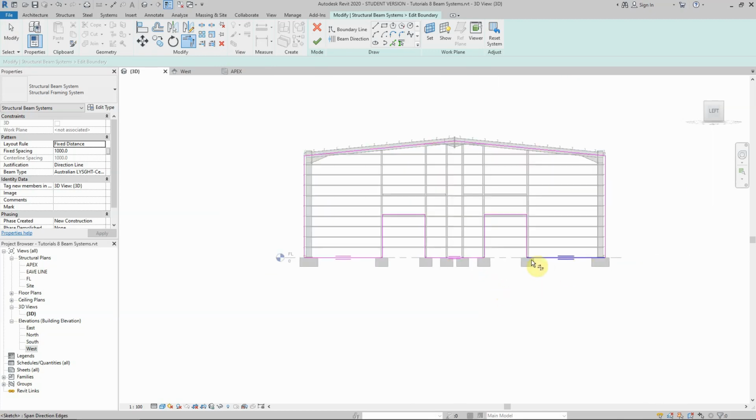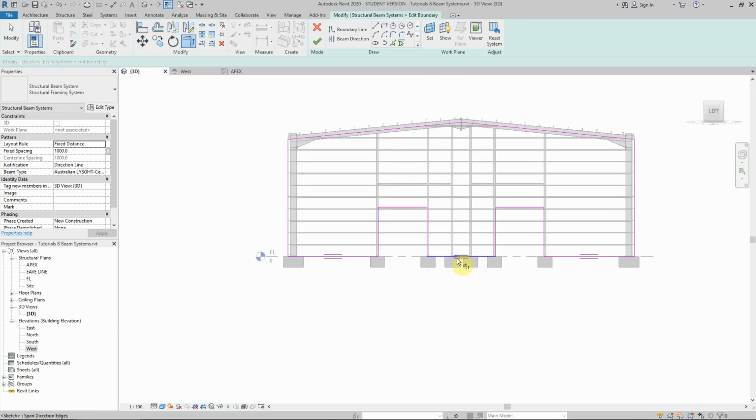So as you can see, I do have 3 lines and I need 3 lines. If I kept one line continuous, that means that will be trimmed here and I have to redraw these lines. But quickly I split them so I can create the 3 lines and then start trimming them. So now we created these boundaries.